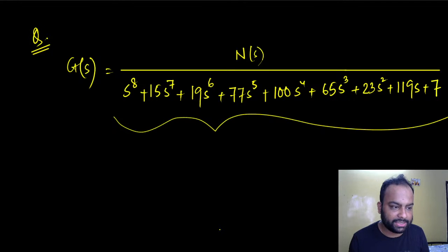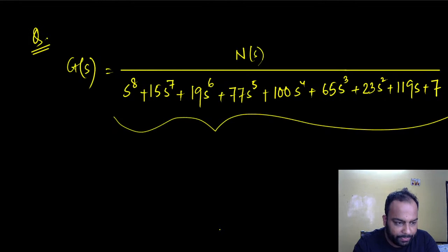I think this was an interesting discussion. With the very simple thing that for us is called a causal linear time invariant system that has a transfer function, we can figure out the system's stability just by looking at the location of the poles and making sure that all the poles are on the left half plane. But this entire thing came from the very definition of BIBO stability, and we proved this entire thing, right? In many control system classes, teachers do try to avoid this entire derivation, but I don't, so that you have a complete grasp on the ideas. On the next day, we're going to learn one of the techniques that we can use to figure out the locations of the poles without actually calculating the poles.